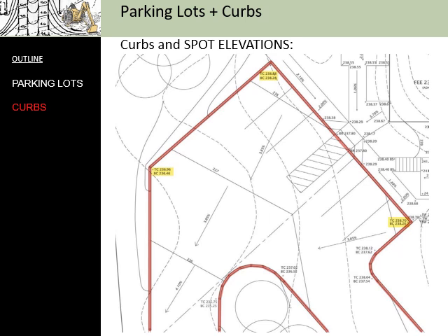And the spot elevations shown in yellow are where there are corners in the parking lot. The spot elevations shown in blue are where there are tangent points in the parking lot. That is, there is a straight line that is then hitting a curved line.